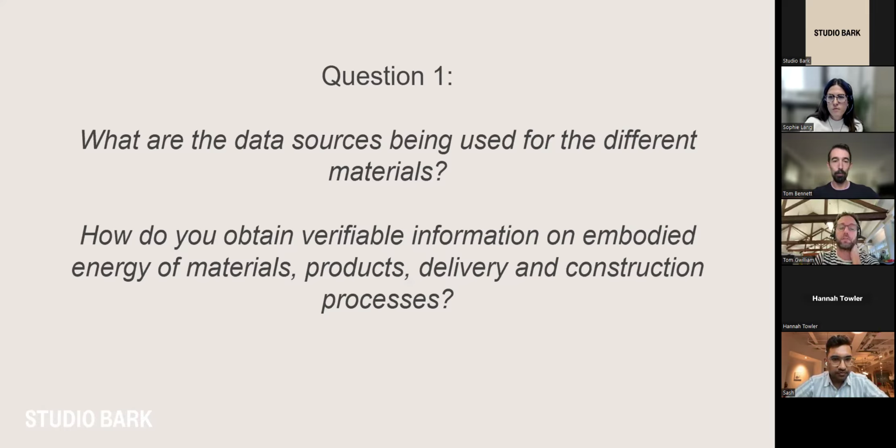There are a lot of other stages before you get to that point, and quite early on in the design stage, which is when a lot of people were using this tool, there isn't necessarily going to be an EPD available, or you're not going to be sure what product to use. So it's good to fall back on the databases. Within the BARC tool, there's a reference to the ICE database, which is a very high level summary of carbon information around very big materials.